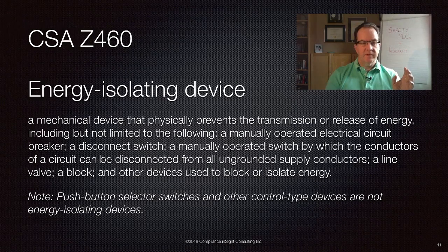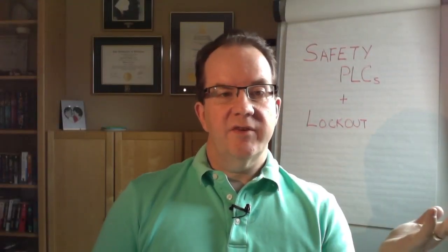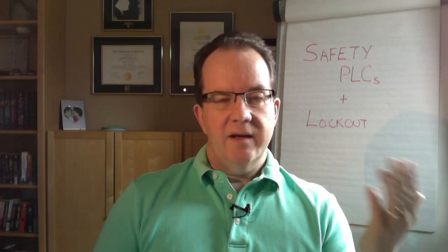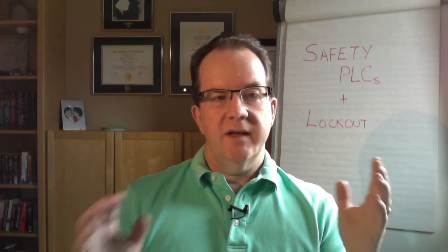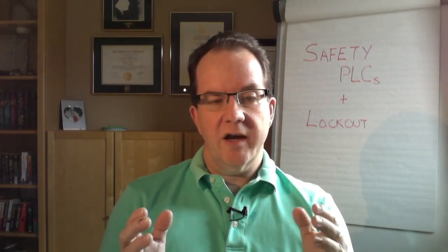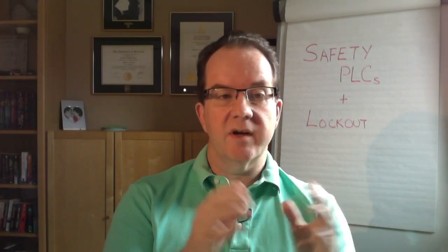All right, so how does all of this fit together? If we're doing maintenance tasks like the ones that are described in Section 75, we need to block hazardous motions, but it doesn't necessarily require lockout for all of those reasons. It might require lockout, but not necessarily.